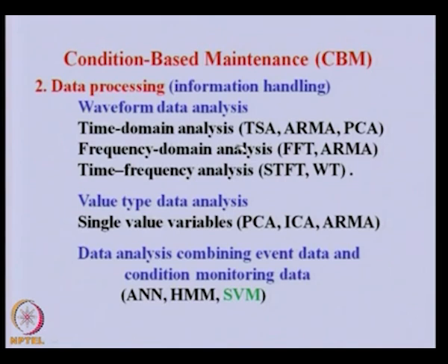Frequency domain analysis, FFT, ARMA model. These are the auto regressive moving average models. These are all time domain and frequency domain models. Time frequency analysis, that is wavelet transform or short time Fourier transform. This kind of techniques are available to analyze the waveform data, such as vibrations.